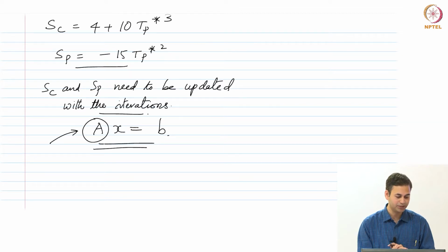Is it clear how to linearize any source term? We use the Taylor series expansion. Now, we had this discussion a few classes before, where would the coefficients be different between cells. In that context we said SP, if it is a constant it would not be, but if SP is a function of TP, then it would result in different AP for different cells. You see that because TP would be different for different cells, as a result SP will come out to be different, which will in turn result in AP being different. So, that will come into play.